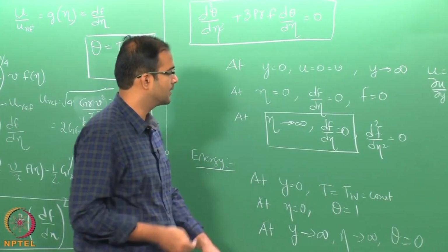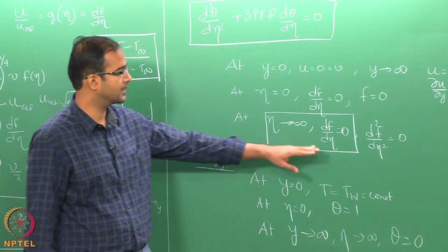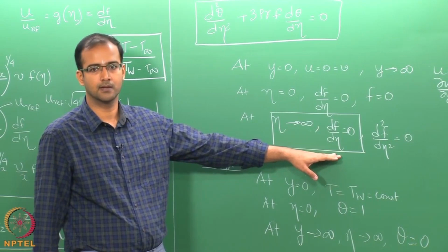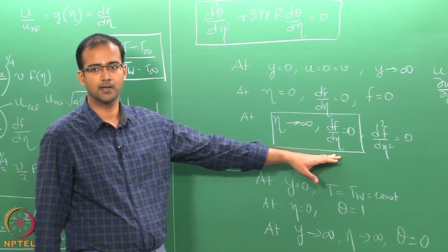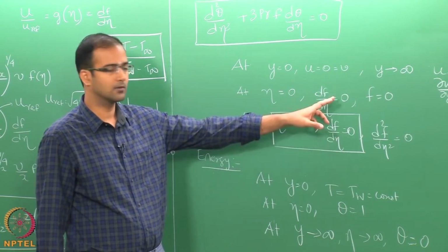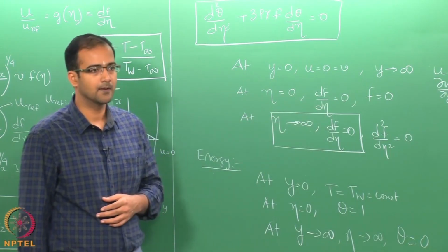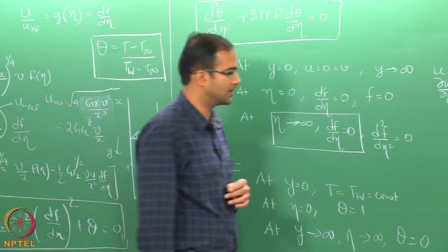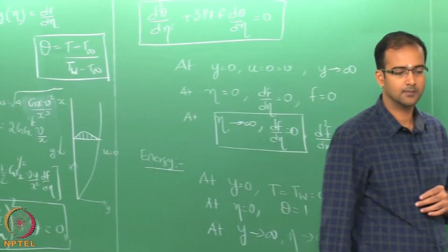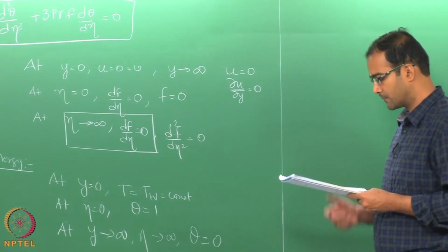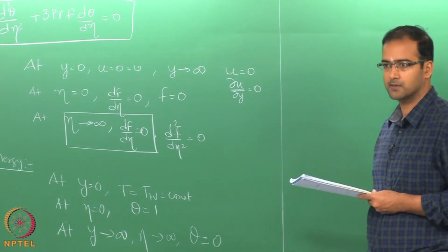Now, if you therefore, look at the boundary conditions, all of them show that these are similar equations with similar boundary conditions. So, you can say that all of them do not involve any x or y components in that. Okay. So, therefore, we can say for sure that we have found a self similar solution to this problem, and the next step is to go ahead and solve it.